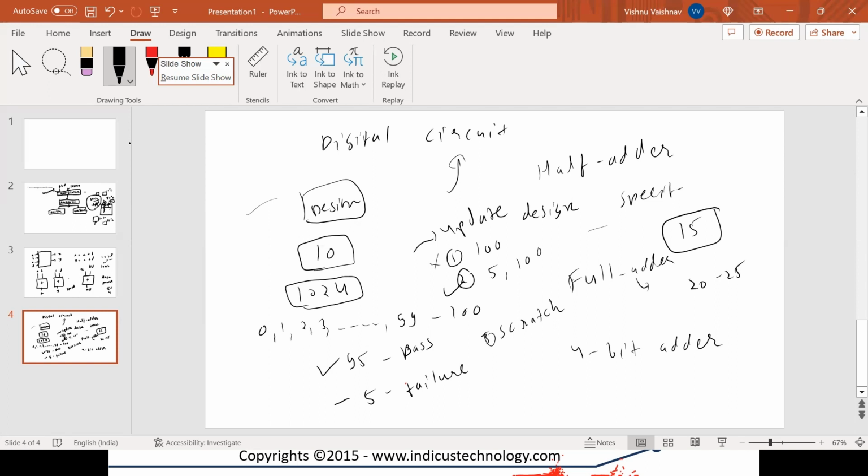And yes, the second approach is good because you should cross check, and it really happens. Believe me, in real-time projects also, when we re-verify the design which is updated because of the previous bug, we actually see the bugs are not resolved properly, and we have a discussion with the designer, and sometimes we again find some real issues. So even the designer should always cross check what verification engineers have reported. Even the verification engineer should always cross check what the designer has updated in the design.